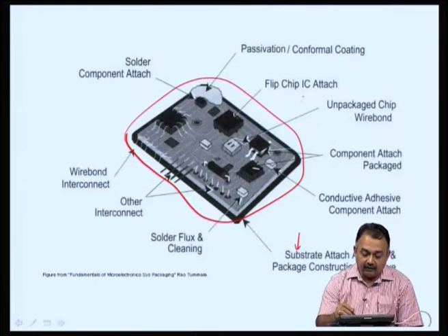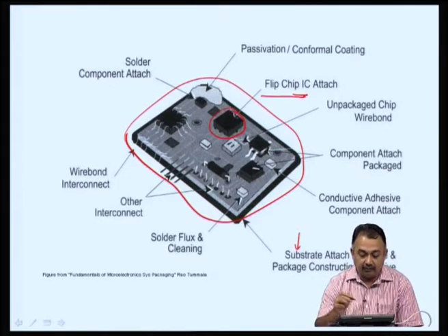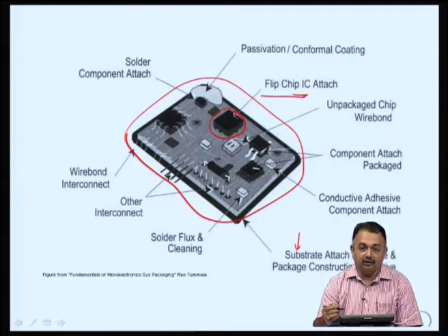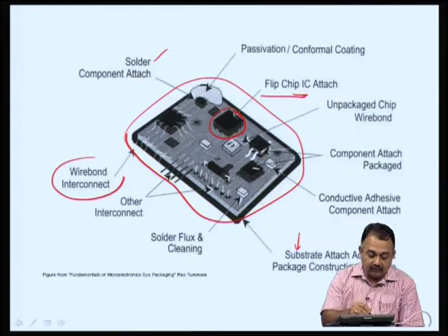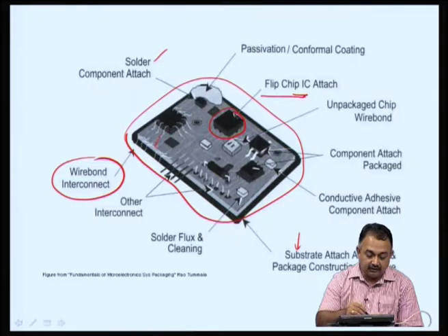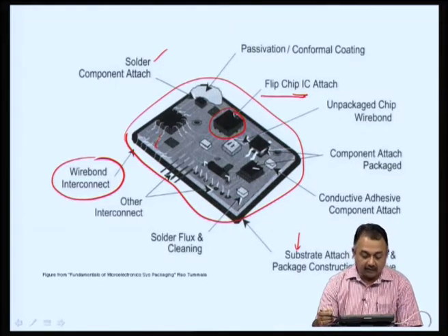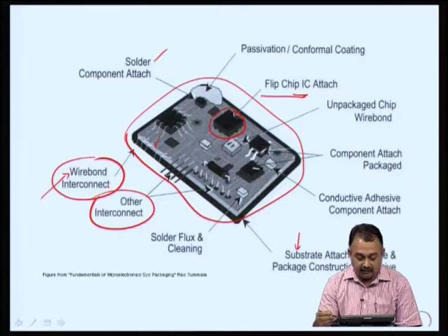For example, if you are using an IC which is of the classification called flip chip, how do you take care of it and how do you protect this IC when you mount this on a substrate that is going to be used for an automobile application? What kind of solder material will you use? What is the interconnect mechanism that you will use within the IC or also connecting the device to the substrate? Is it a wire bond or some other connection choice? We are going to see that.